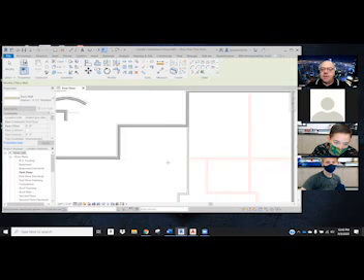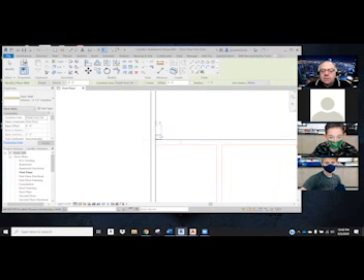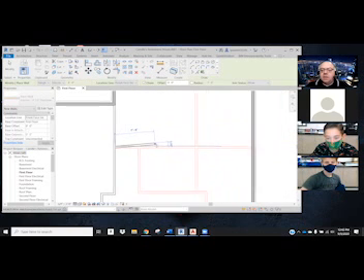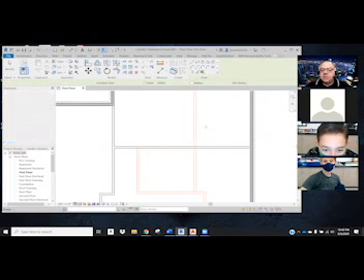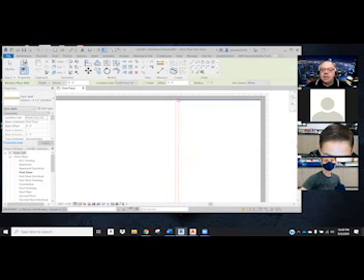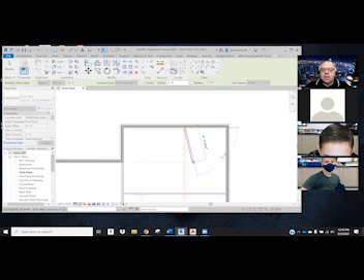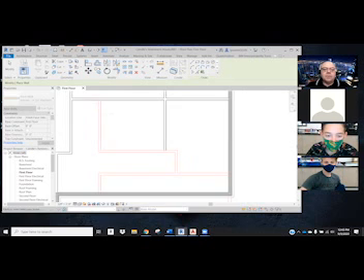Okay, and that puts that up there. Again, I want my walls to be as long as I can make them. It's how they're going to build them anyway, and so it just saves a little bit of work if I just draw them that way. What they do is they build the wall laying on the floor, and then they tilt it up into position. And so if I think about it that way, it makes the drawing a little more realistic and a little bit more manageable because now you're understanding what the framer has to do. And I'm just going to crank these out just as quick as we can.